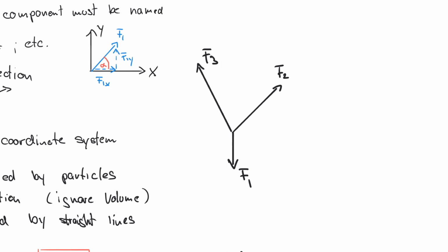So the first thing you need is a component for each of these forces. So let's do that. And remember that when we draw components, we always have to include the direction. So let's say this and this and this. And we need to include names: F2y, F2x, F3x, and F3y. And that is still not done, because remember, we need to include angles. So let's call this alpha and this beta. Of course, you use numerical values there sometimes. But now we're still not done.